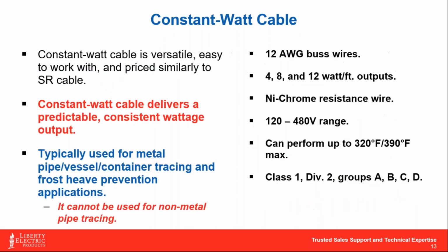Okay. All right, so constant wattage cables, that was the lengthiest one right there. If you made it through that one, the rest of this should be cruising. So constant wattage cables are exactly what they say they are. They are going to put out a consistent wattage per foot. There is no fluctuation, no roller coaster effect where I've got to worry about computing out what the maximum wattage per foot is.